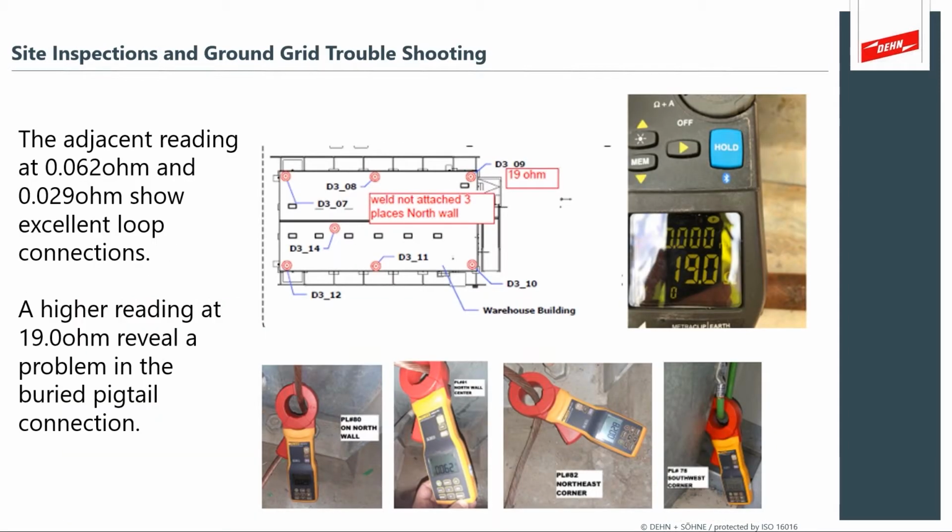So you're on your site and you're inspecting that earthing system. And what's really nice about a slide here is that we can use a clamp-on meter that is an active source. It actually has a send and receive type function. Think of it like sonar for your earthing, where you can ping into the pigtail and it will tell you that it's hearing that ping return, and it calculates the impedance.